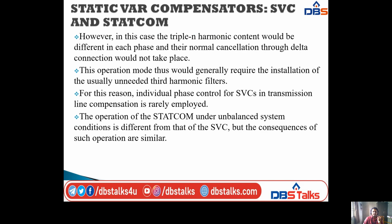However, in this case, the triplen harmonic content would be different in each phase, and their nominal cancellation through delta connection would not take place. So this operation mode would generally require the installation of the usually unneeded third harmonic filters.